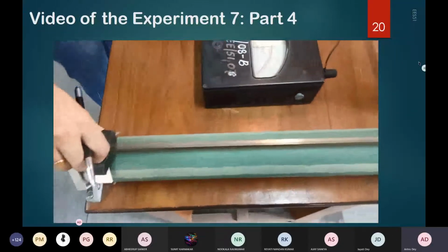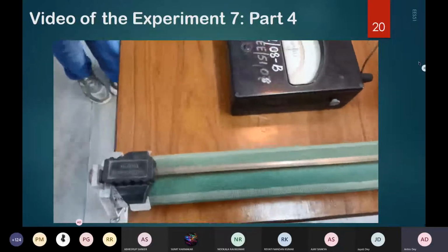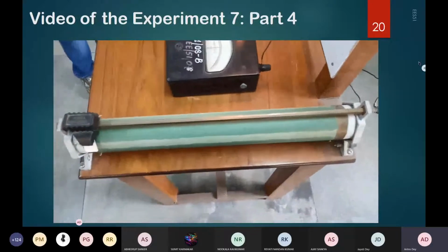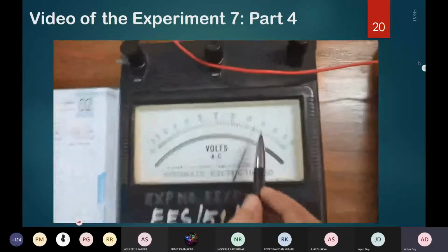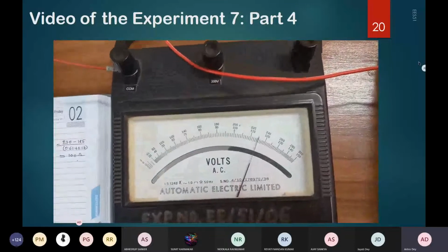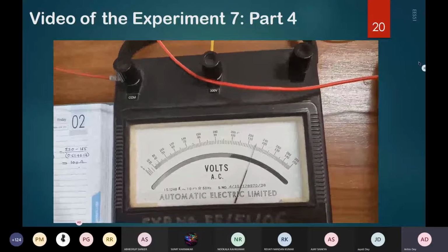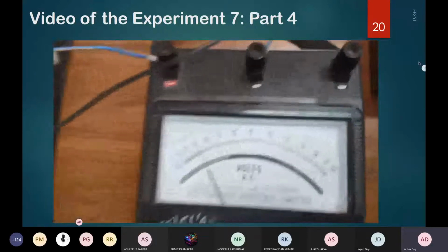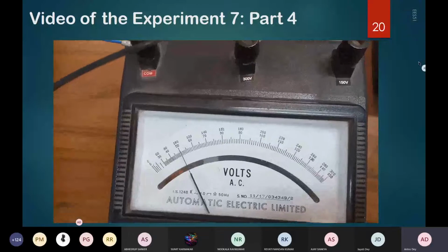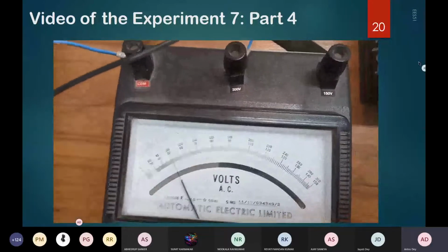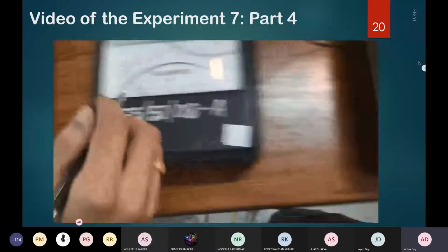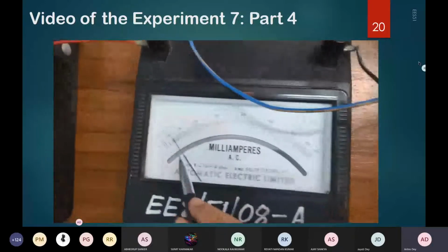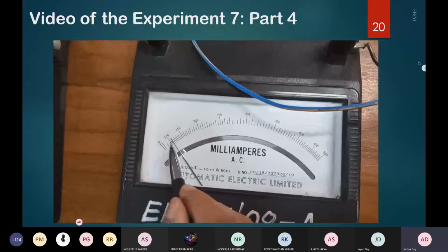Here we'll set it to 200. This is the maximum resistance, which is 200, and for that we just record the voltmeter reading. The voltmeter reading, if you see here, is 230 as usual, because we keep it at its maximum value, and then the drop across the lamps will be how much? It is 105 or 110, between that. So let us take 107, and then we record the reading across the carbon filament lamp. This has come as 110,